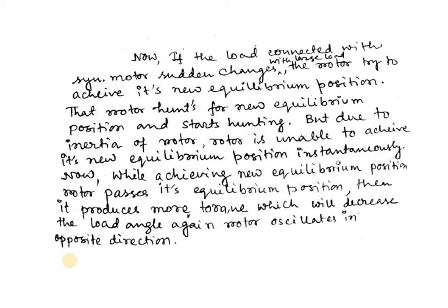So here something is to be highlighted: when a synchronous motor experiences sudden changes with large load, the rotor will try to achieve its new equilibrium position. When a sudden change in load occurs, the rotor will first feel the effect of the load change, so it will start oscillating and try to achieve its equilibrium position.